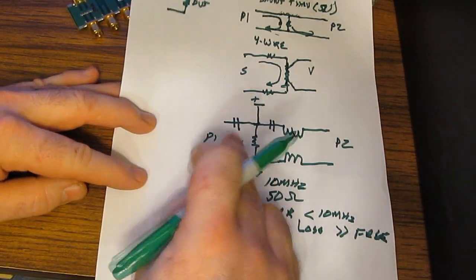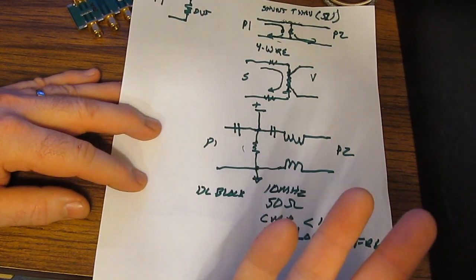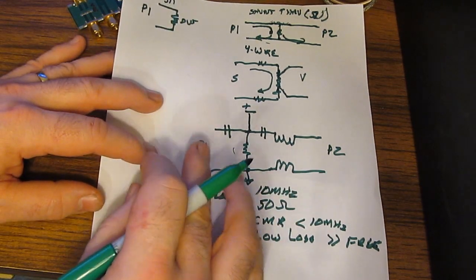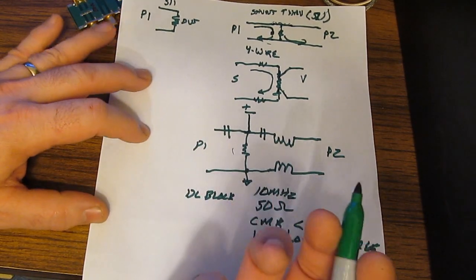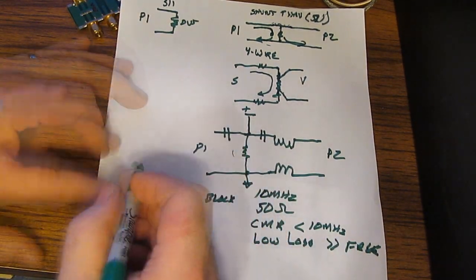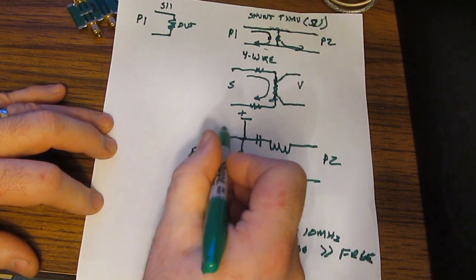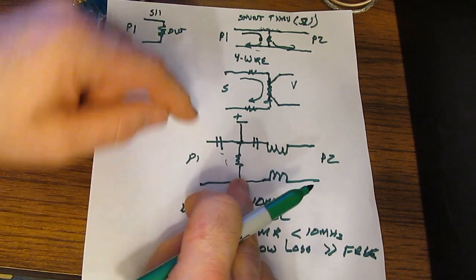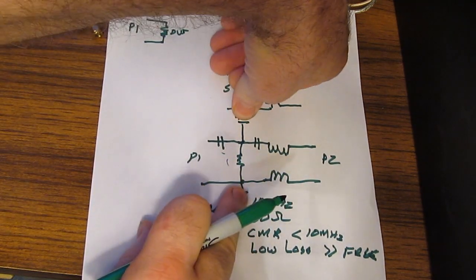A capacitor impedance for DC is, sure, it's very high. It doesn't pass DC, but it does pass AC, and the higher the frequency, the impedance is going to go down. So what ends up happening is we connect our network analyzer up with our DC blocks, and we think it's going to save it, and then we apply power to the PDN.